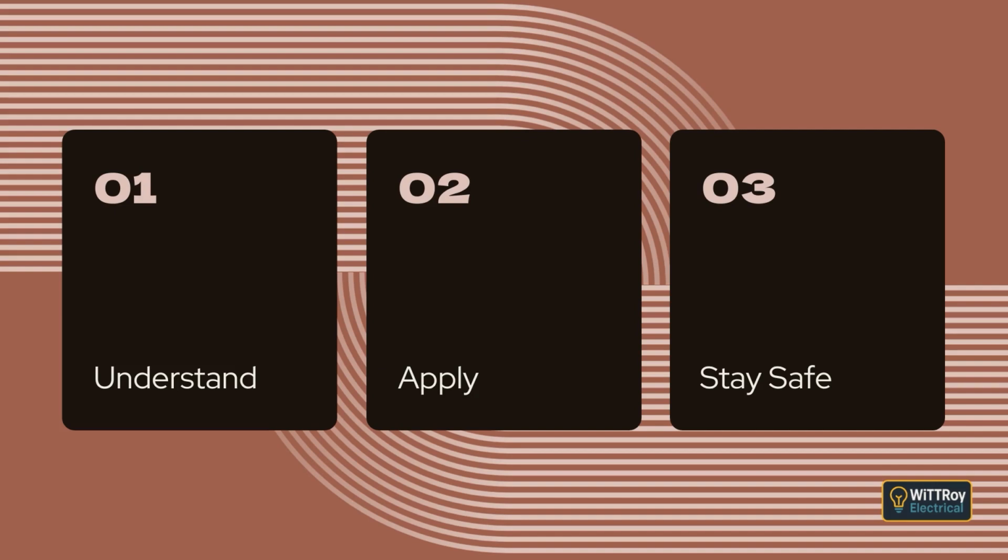Clause 3.9.8.4 Proximity to non-electrical services. Wiring systems must not be installed near services that produce heat, smoke, or fumes unless shielding prevents damage. Wiring below services that may create condensation must be protected. Electrical services must not interfere with the operation of adjacent services. Wiring must be protected from hazards created by the presence of other services.